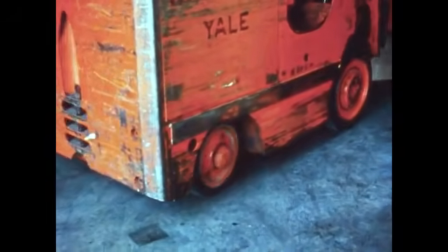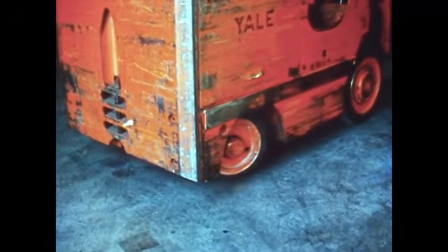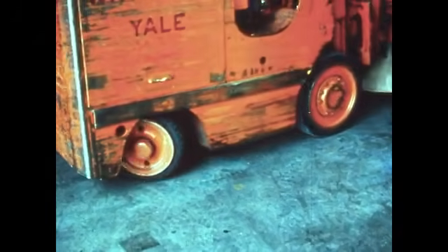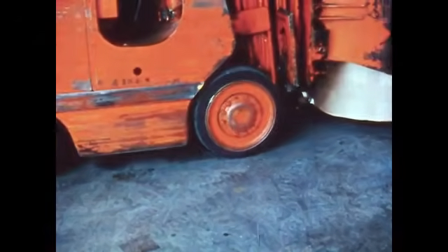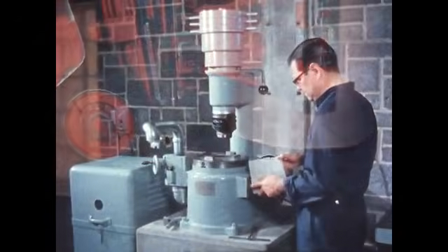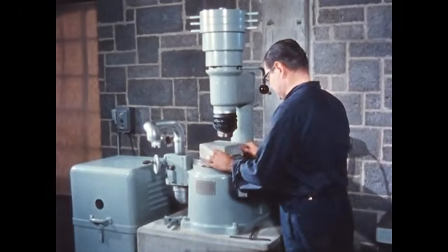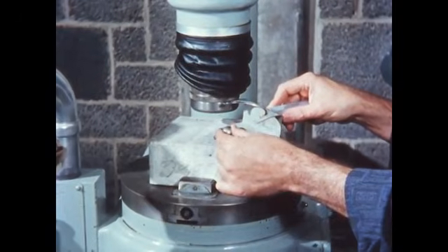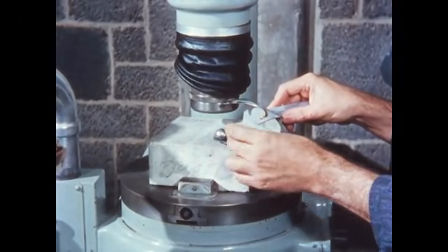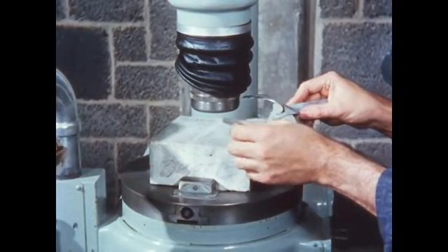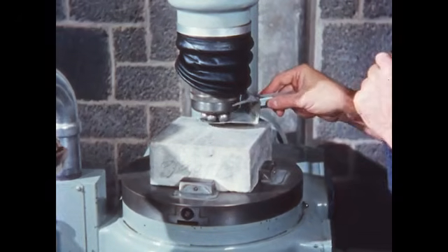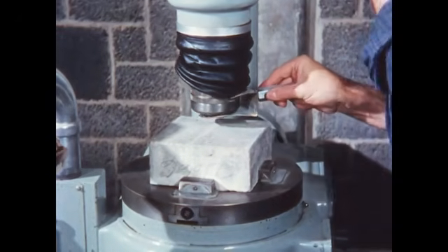Concrete floors and pavements must stand up under heavy and continual traffic. Concrete, therefore, must resist wear and abrasion. Abrasion resistance is difficult to measure, but relative values can be established. A specimen is ground under rotating steel balls loaded to a constant weight. The specimen is weighed before and after the test. The weight of concrete worn away in a specified number of revolutions indicates the wear resistance of the concrete.